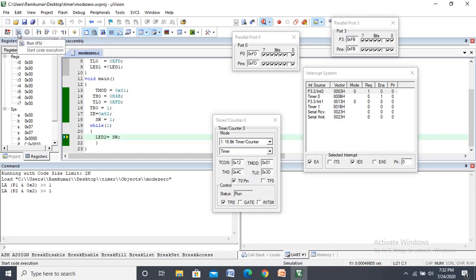Now the entire program is going to execute. Just look at TF0 over here. It is running with the clock frequency of 11.059 megahertz, so you can't watch TF0 being set, because it is running at microsecond clock speed. It keeps on counting the value. Once it reaches FF, TF0 is set, and it goes to the ISR program. It complements, again complements, again complements, so this particular bit toggles.